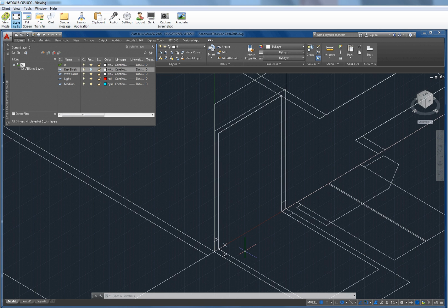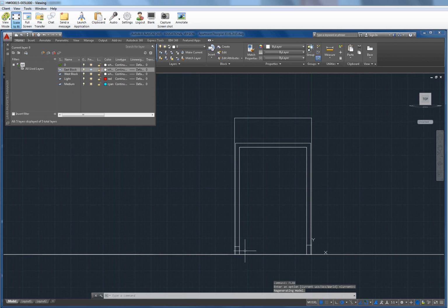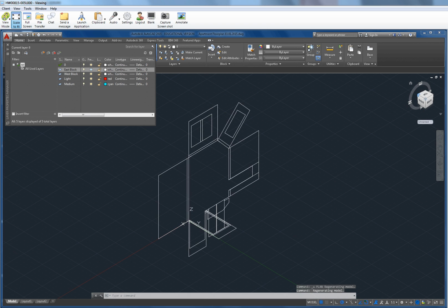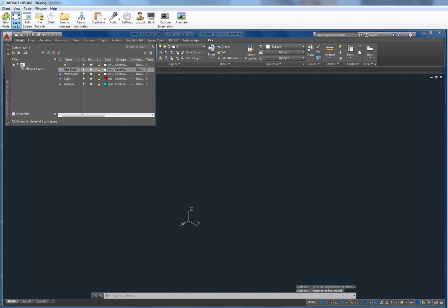And this might actually, I want to be on the other side, right? So I can do UCS Y180, because I might want to be drawing on the inside when I go to plan now. Yeah, it gets tricky because you can see now the whole orientation of what's top and what's bottom, what's left, is based off of world, right? So my front is over there, so it's hard to coordinate what view I want to be on. Even when you think you have it logically figured out, it won't do it.